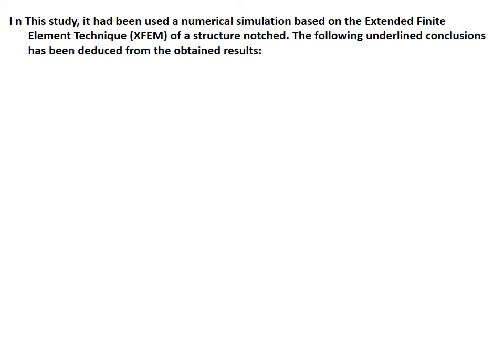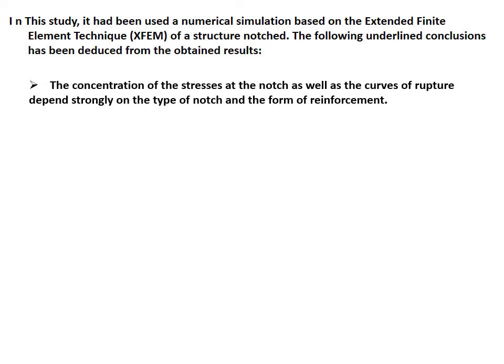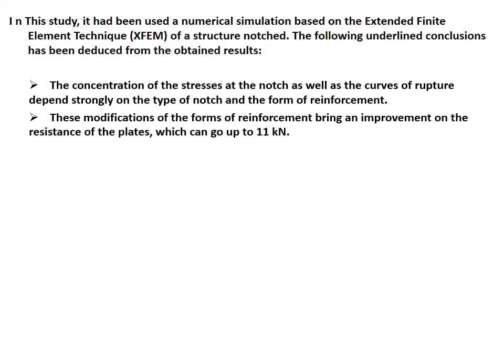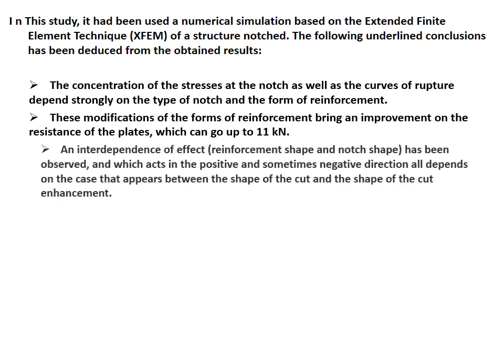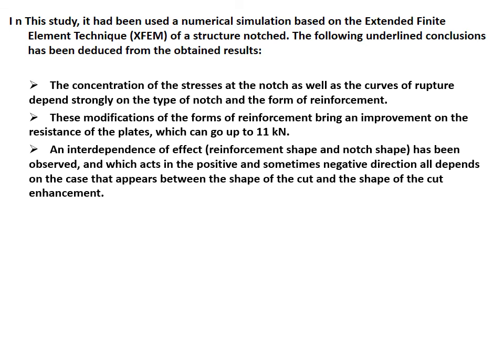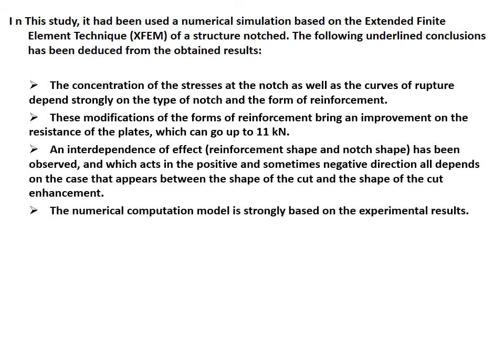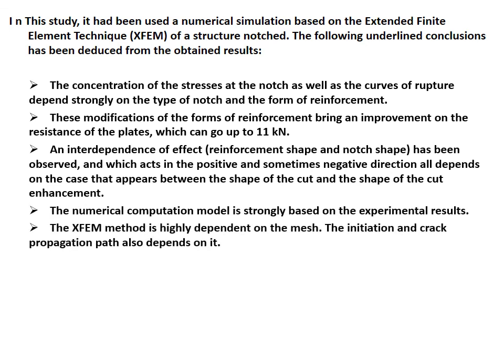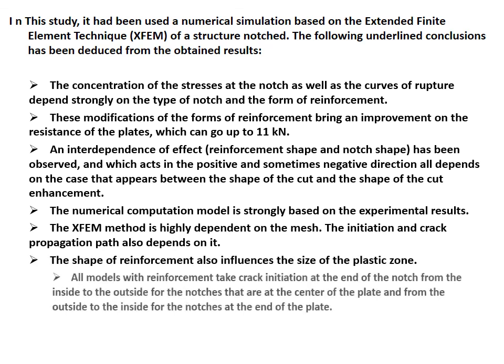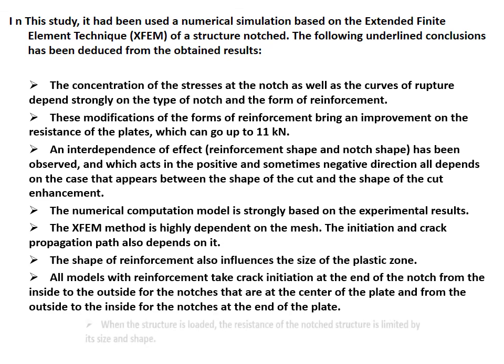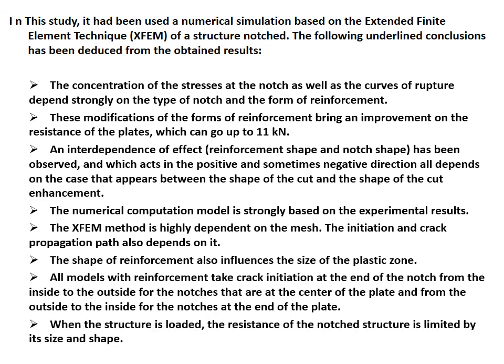The composite patch, whatever its size, ensures slow transfer and reduces the concentration of stresses in the damaged plate. The geometry of the edges of the patch is important in order to reduce the stress concentration at these edges. The square or circular patch exhibits the same response in the strength of the damaged and repaired plate in terms of tensile strength. The modification of the height and width parameters of the patch, as well as the geometric shape of the parts of these edges, must be optimized in order to ensure a good quality of